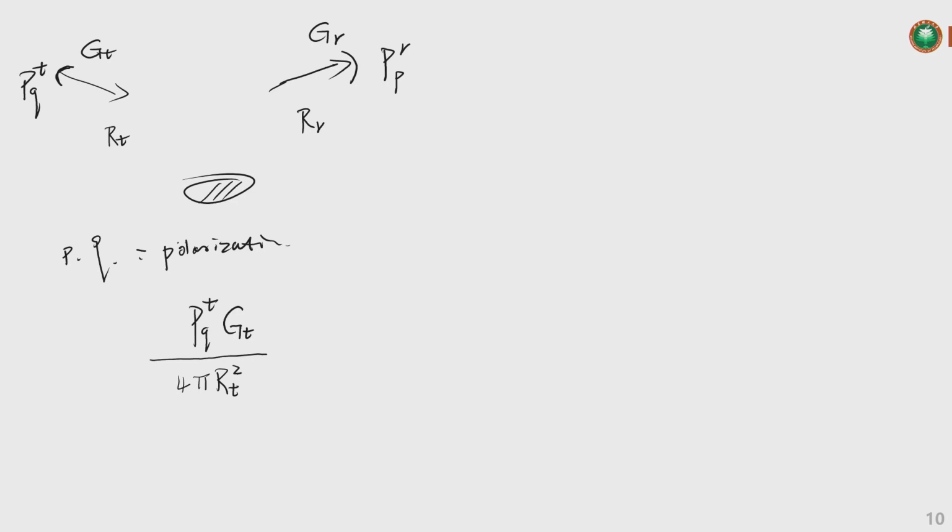And then, after it reached, or it launched onto the target, then it was scattered away, alright, to the receiver side. So we assume there is another term, the radar cross section, sigma. The incident is Q, output is P, polarization, so it's sigma PQ. So it's radiated out now, and it's collected by the receiver antenna at the receiver side.